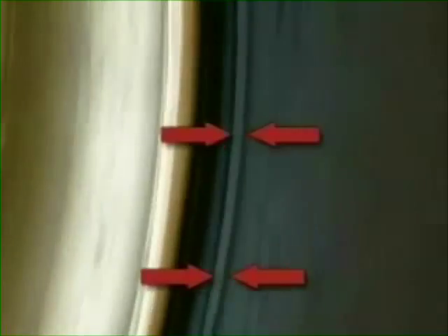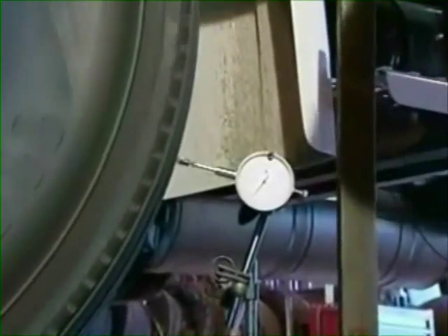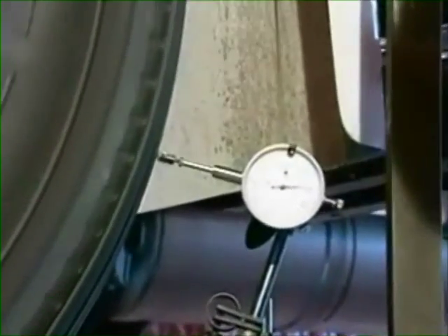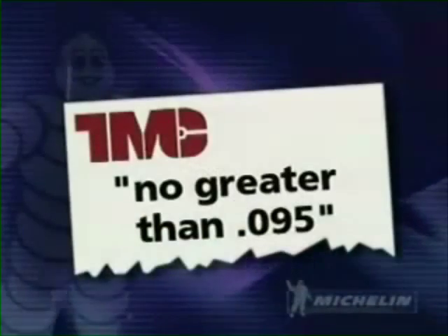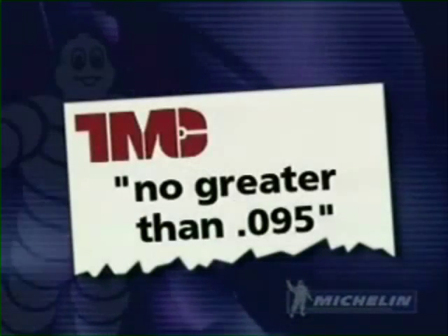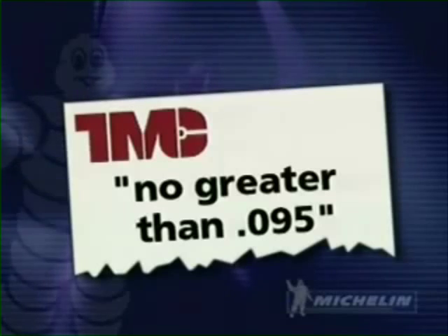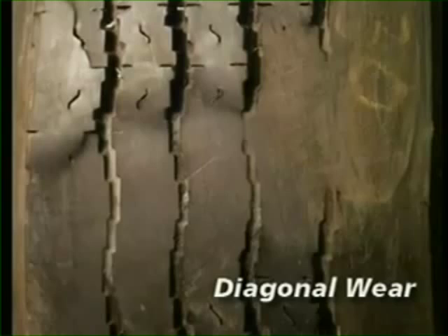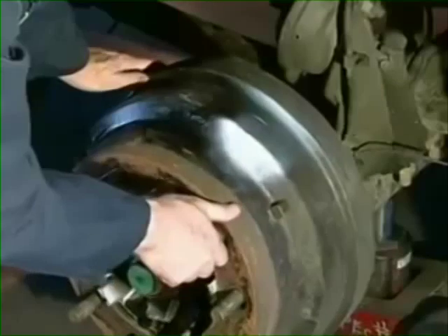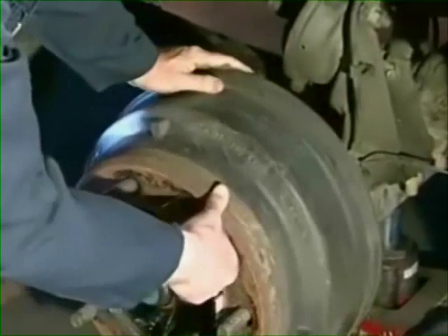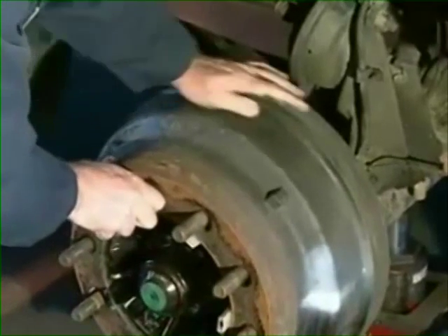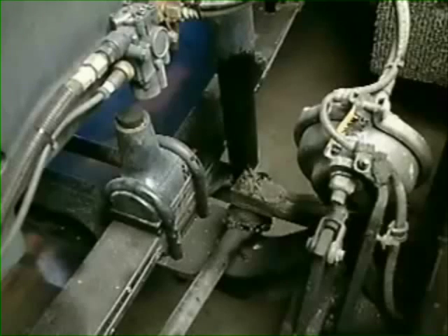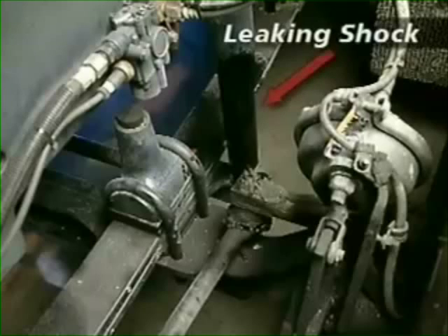Number 2, the front tires are mismounted on the wheel. Number 3, the front tires and/or wheels are out of round. The tolerance for a tire wheel assembly is 95 thousandths of an inch measured radially on the tread. Number 4, the front tires have developed flat spots or diagonal wear on the tread. Number 5, the brake drum is out of round or out of balance. Or, number 6, the front suspension components and/or shock absorbers are worn out or broken.